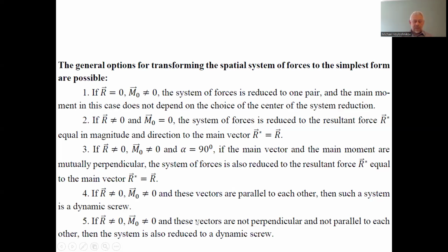we have to first find the projection of the moment onto the plane in which the force lies, and second, the projection perpendicular to the plane where the resultant force lies. The second projection we can decompose into a pair of forces of the same size as the resultant specified for the assignment.